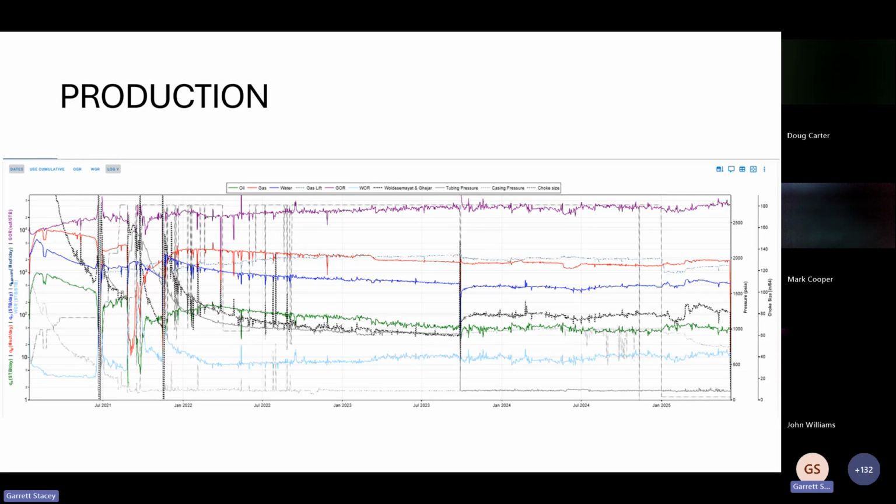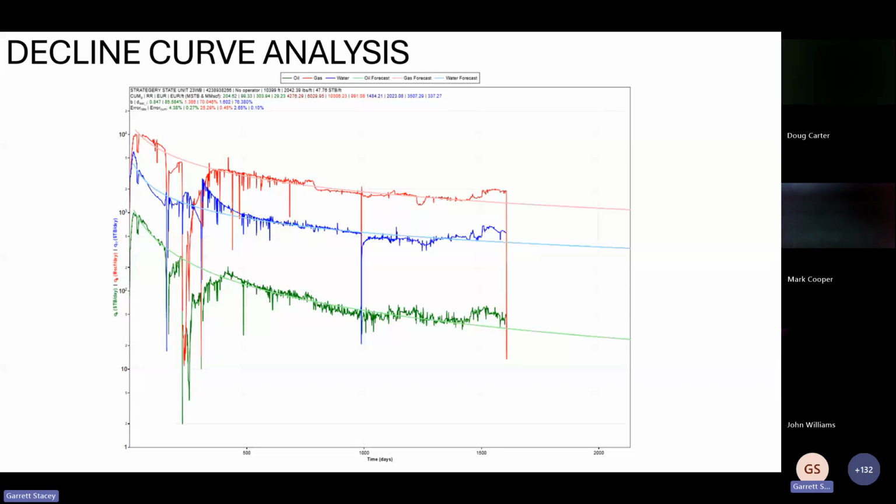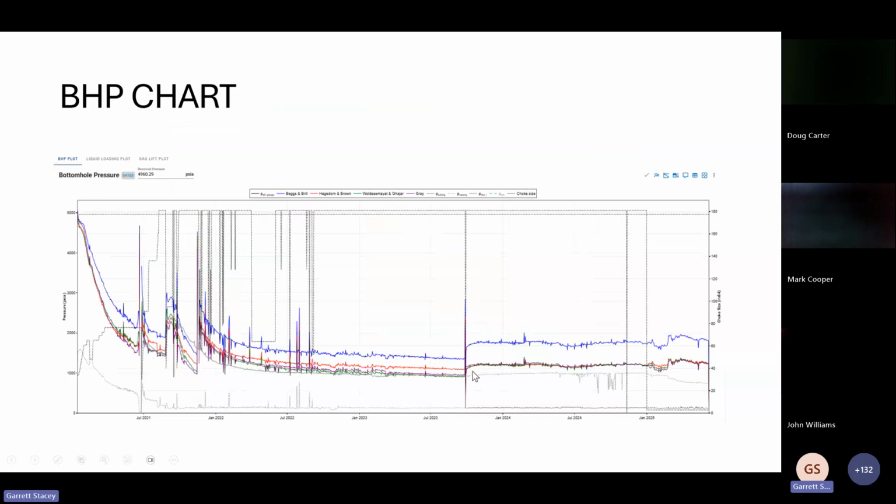If you scale up your tubing in your tubing, you can just pull it. Whereas if you scale up your tubing into your casing, it's a lot harder to fish that out. So that's what took place right here, where you see a big drop in rates. That was our change from annular to tubular flow. So the decline curve analysis that I auto fit before making any of my changes, you can see then that the changes were positive. The bottom hole pressure chart, again, this is where we changed our rates.